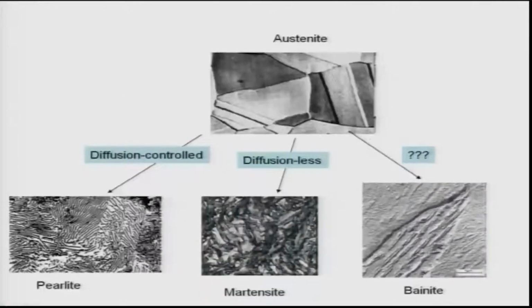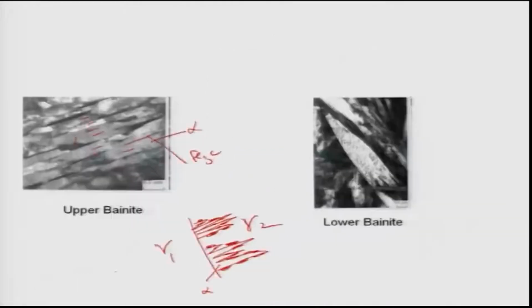Pearlite has parallel lamellae of alpha and Fe3C. To make sure, pearlite looks like this. You see the picture here. It has parallel lamellae of cementite and alpha. But on the other hand, here cementite is precipitated on the boundaries of the alpha needles. Therefore, these are not the same.